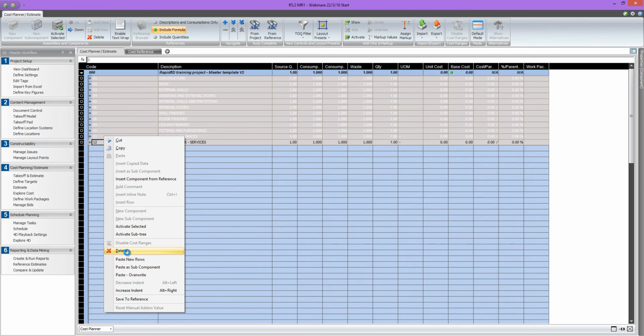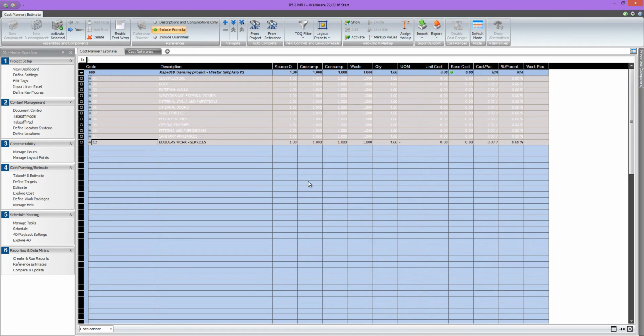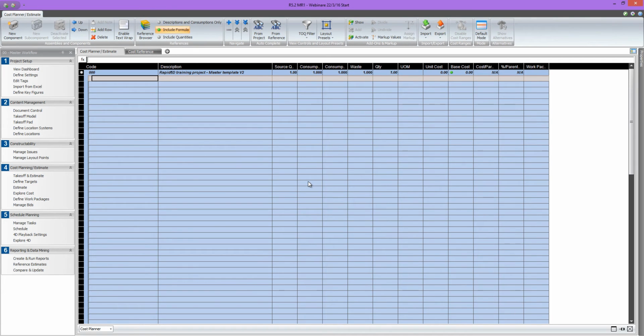Anything we're about to do now can be done with the cost planning NRM1 structure or with this bill of quants, but just to show you the cost planning, we're going to do it with that side of things instead, but I could have kept the original bill of quants and continued on that way. So to start with, I'm just going to show you how to do a manual cost plan here.